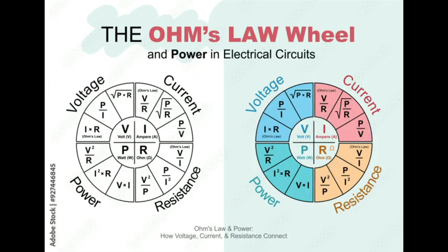Now, most of our circuits receive 120 volts. So I will be sending 120 volts to all of the lights. That's going to be a constant pressure that each one of them is going to get. Now, because all of them have the same resistance value, or the same wattage, I'm assuming that they're all gonna have the same resistance, right? It's gonna be the same throughout the whole circuit.